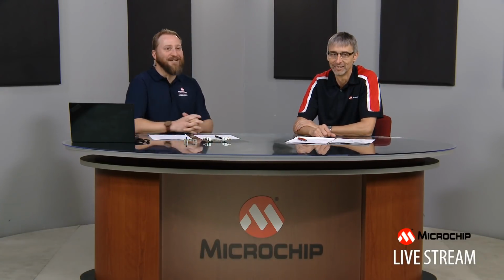Stefan, anything to add to that? No, fundamentally, you can configure zero drift amplifiers very similarly to how you would linear amplifiers. So fundamentally, there's nothing that would prevent you. Again, you want to look for preserving what you're buying in the first place. You're buying all this precision, and you want to make sure that you preserve it when putting components around it. For example, opting for very high values of resistors is probably not a good choice, because the resistors add noise. They would have a drift component to it, and so forth. So you want to be mindful about not destroying what you paid for in the first place. Right. Good point. Okay.